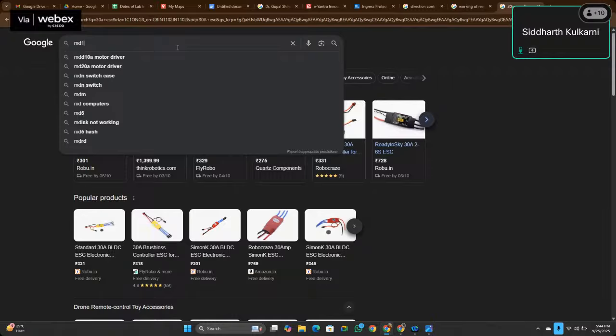Got it. So basically, based on what type of motor you are using, you need to change the motor driver appropriately. Typically, PMDC motors will tell you the wattage of the motor rather than the RPM or current requirement. Wattage is power, and power is equal to voltage times current. That's the equation. Based on that, you can figure out, if they are giving 100 watts at 12 volts, the appropriate current according to the calculations. So that's the basic idea.